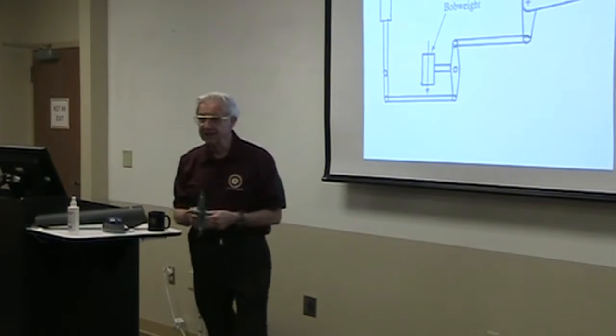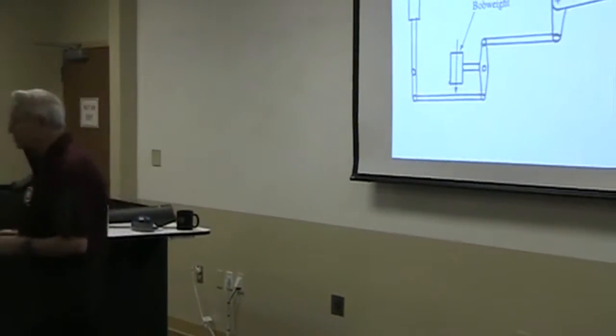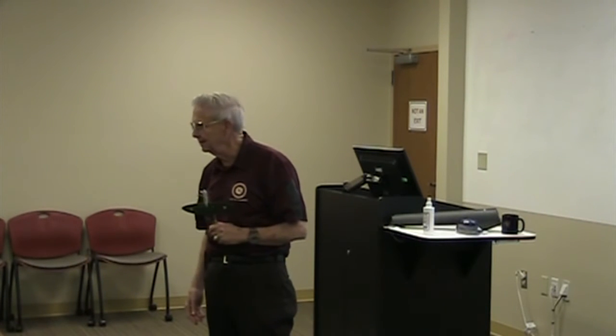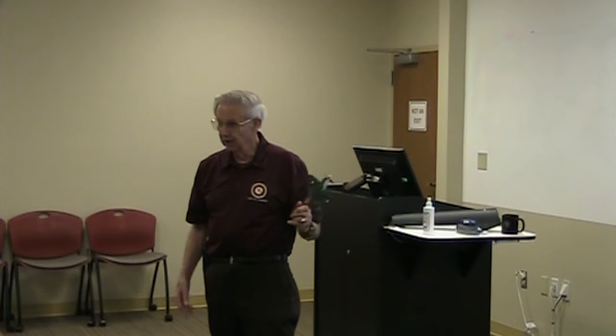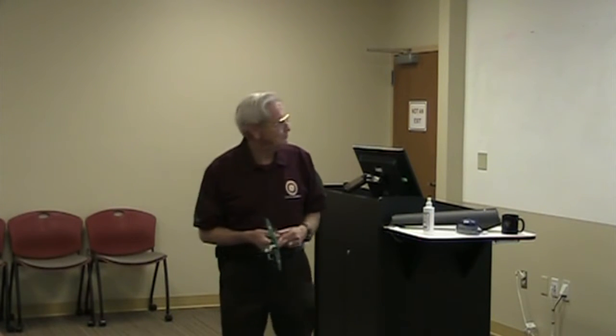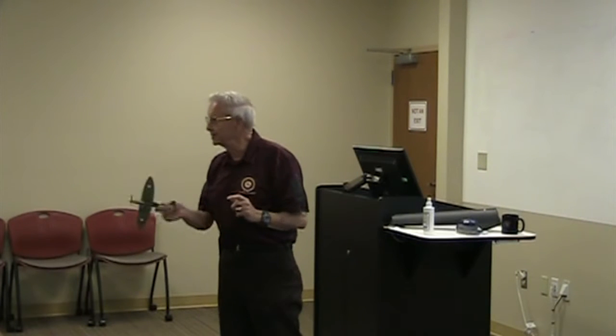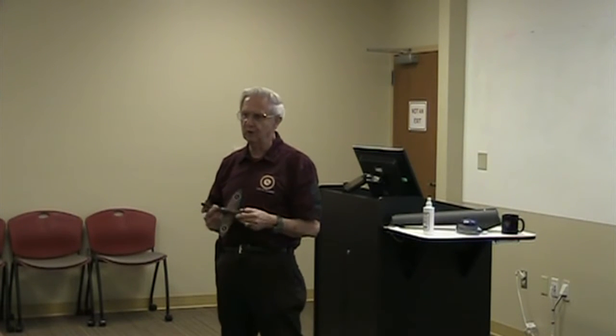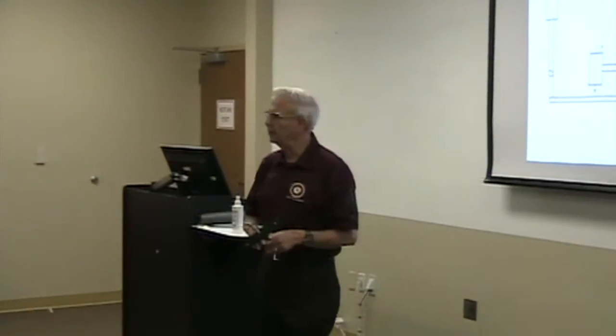Neat thing about this is, for maneuvering, what happens to that weight? Let's say you're at 2 G's. That weight was 5 pounds originally. What does it weigh then? 10 pounds, right? So the bob weight increases maneuvering stability also. And so a lot of airplanes, when the FAA came out with that requirement, started putting bob weights in rather than downsprings.